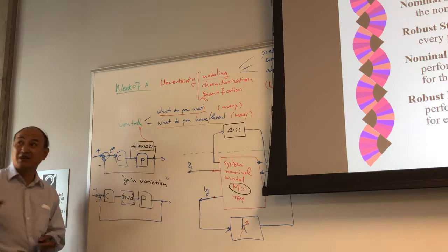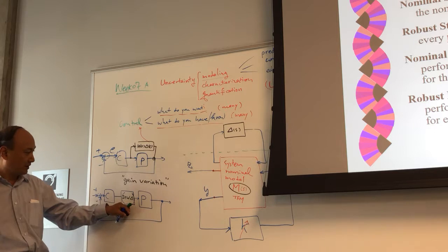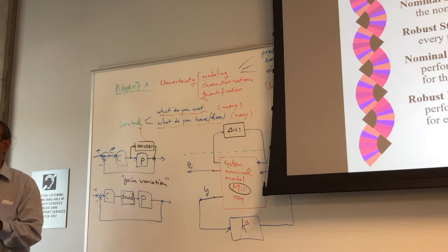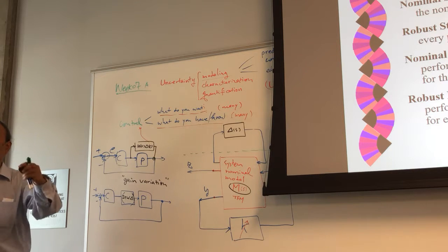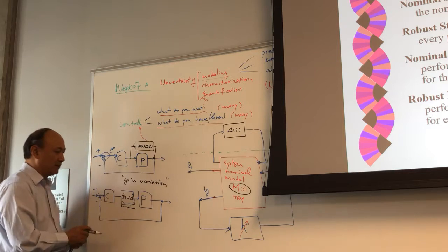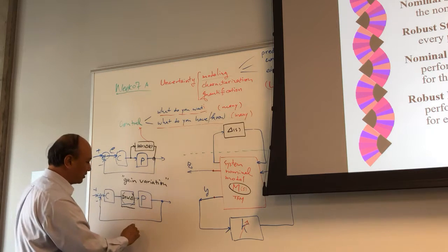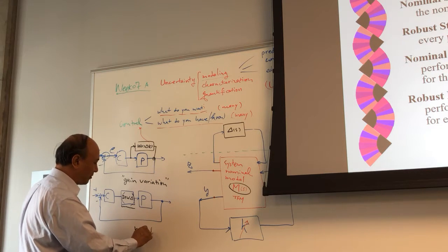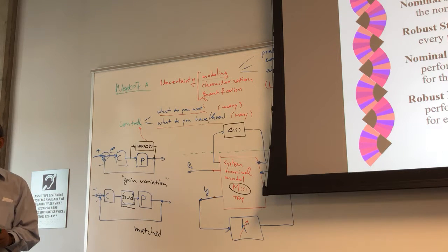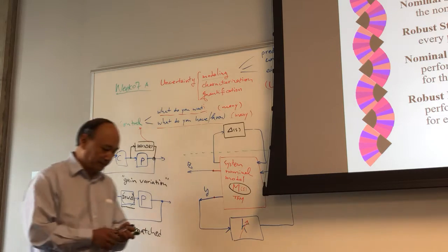So this is something you can pull out like a gain variation. It's not exactly true. In the SISO case, yes, it's like a gain variation, but in here, it's not a gain variation, okay? It's just on top of that. So this can be regarded as a gain. So you can pull out this one. So sometimes this is called matched uncertainties.